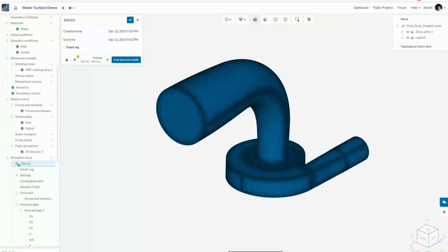Yeah. I wanted to talk to this one, actually. Will recirculation result in cavitation? Possibly, but not necessarily. I guess the bigger cause of cavitation is lower pressure. Recirculation is normally where the flow is a lot slower. The recirculation is more about wasting energy at the end, where the water's burning up energy and not giving it to us in the form of rotation of the rotor.